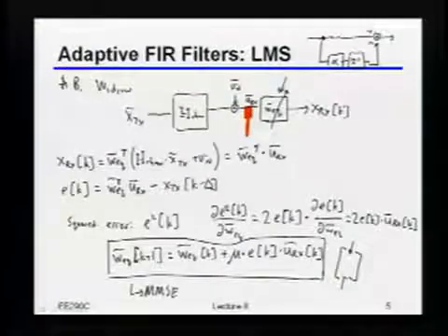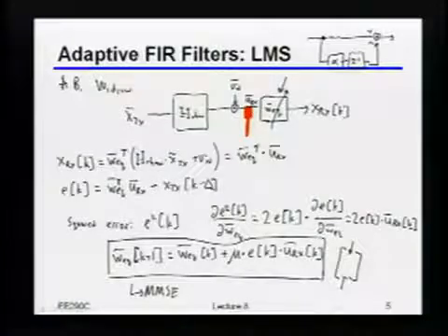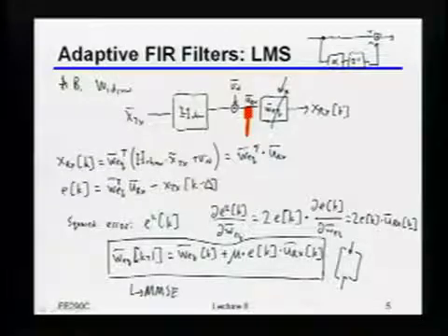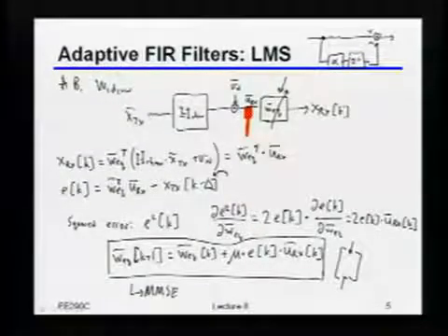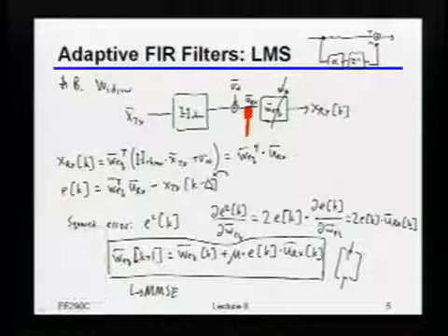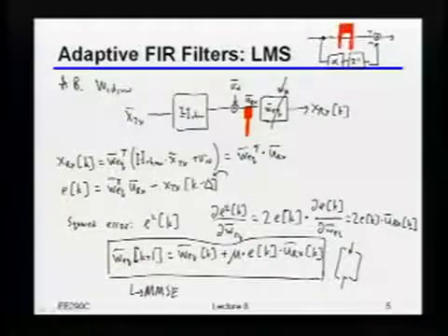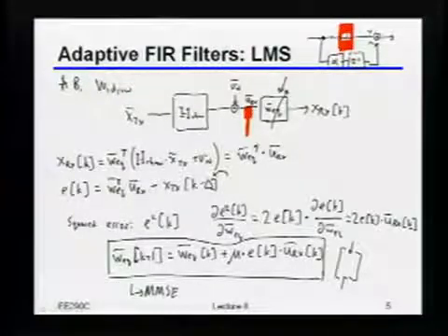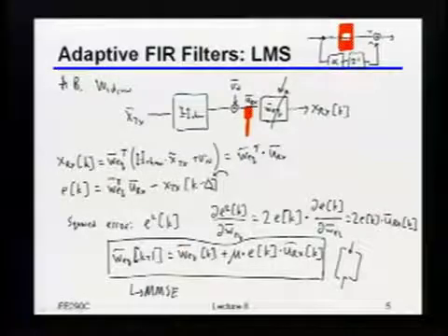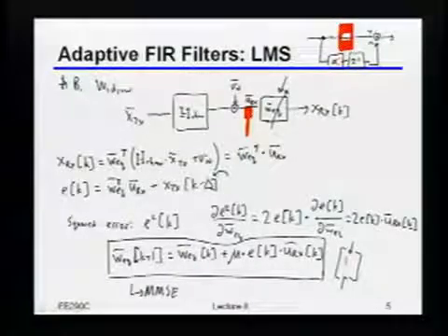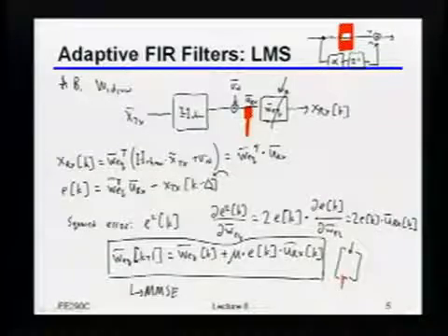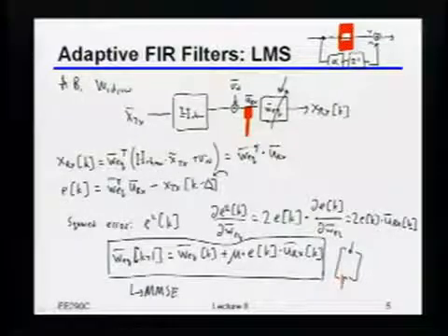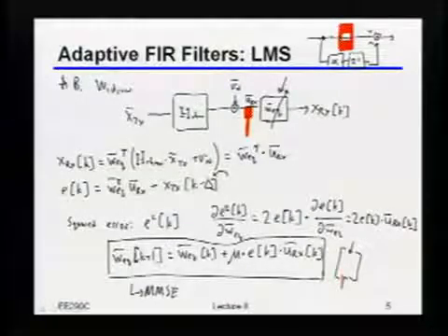So does the delta accommodate only for the time shift in the channel, or does it compensate for the number of taps that are behind? This delta is really compensating for the time shift of the channel. Right, but what I'm trying to get at, and unfortunately this is a slightly bad example, is that if I was tuning both of these, maybe it would be more clear. If there was an alpha and a beta there, then for the alpha, all of these k's would line up. But for the beta, when I move one down in the vector, that's one bit ago. Then again, when I go to the next sample, one bit down is one bit ago. Does that make sense?